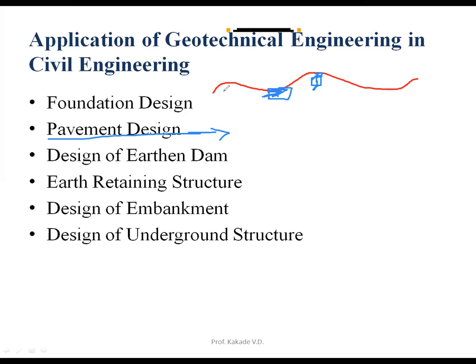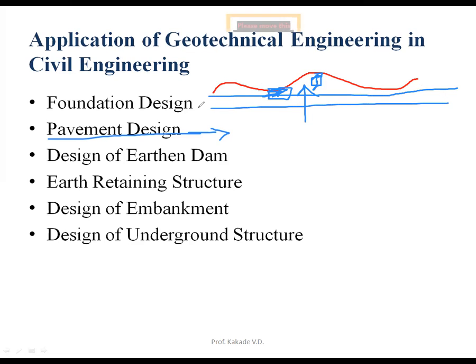These pavements rest on the ground, and that ground should have its own reaction. We have to consider whether the ground has sufficient bearing capacity, or what kind of reaction takes place on the road, whether it is applying uplift pressure or not, whether there is some kind of leakage, what the permeability is. That kind of thing must be understood before designing the pavement.